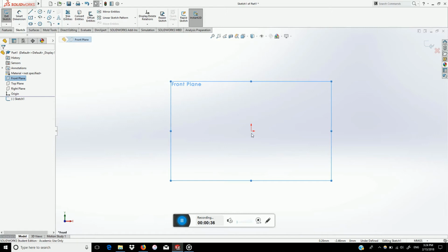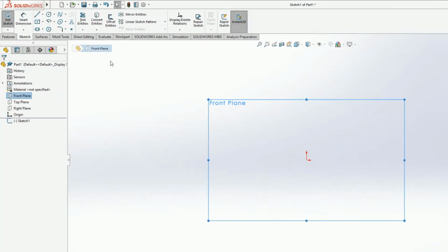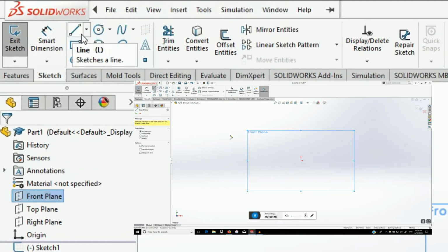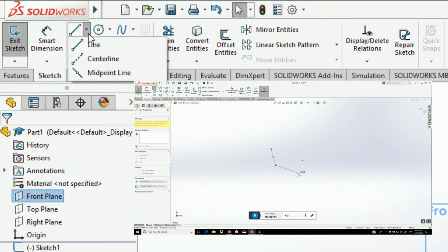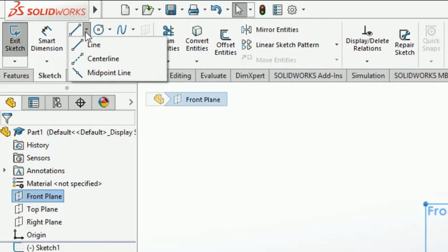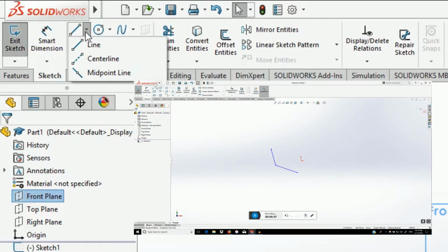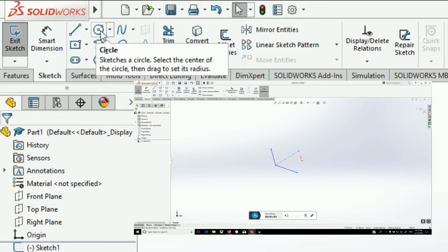All features can be used differently, but we will cover the basic and important use of each element. SolidWorks' illustrations and descriptions are good in explaining how they work. Lines are used to draw straight lines. You place the initial point, then you place the next point, and then the next. When you want to finish placing points, just press Escape. You can also use a center line, which will only display for geometric and sketching purposes and will not count toward the sketch when it is used for a feature.